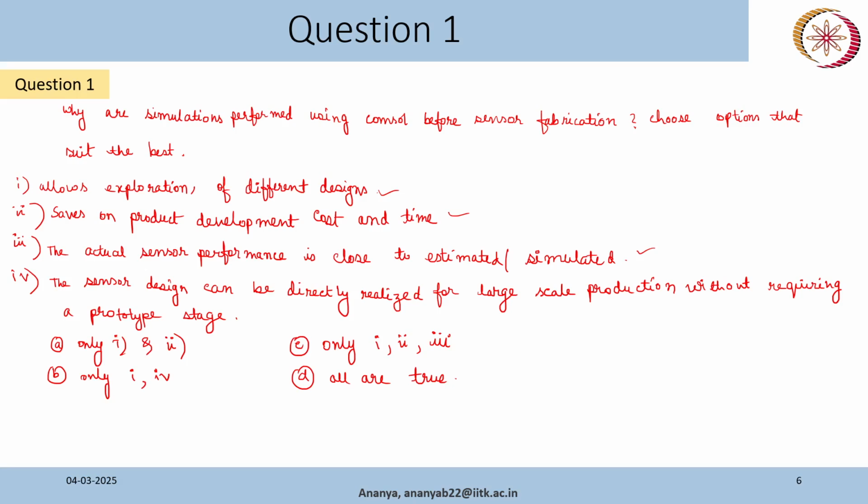Say your material property can be a little bit different, right? Say you are using a thin film of some material, and you are using the inbuilt material properties in COMSOL. You are using a material for heat flow control, and you are using the thermal conductivity, which is a standard value already given in COMSOL.